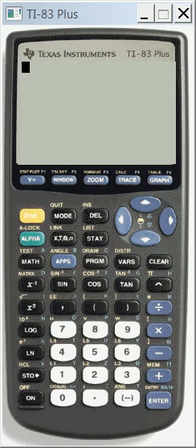use the curve, where in fact the friction factor was a function of the Reynolds number, which meant that it varied no matter what the velocity of flow was. Of course, the other cases would be where you have a rough pipe, when very often you can just pick the friction factor first and you'll be correct on your first iteration.